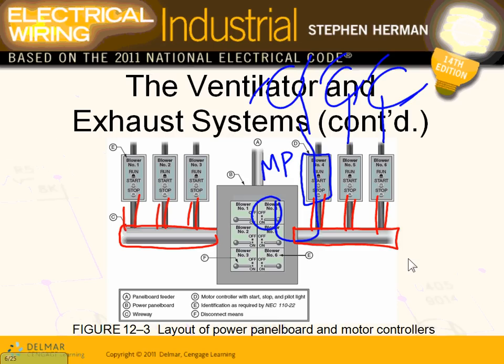So if you are working for electrical contractors, really pay attention to this. This is a really nice system. What's the alternative? Bringing all these conduits directly to the panel. But that's it. So my job and your job is to size the mechanical panel, bring the feeder to the mechanical panel, and take the feeders out of the mechanical panel to that mechanical equipment and size them accordingly. I have no doubt that all of you will be able to size it. Why? Because they're horsepower at a certain voltage.